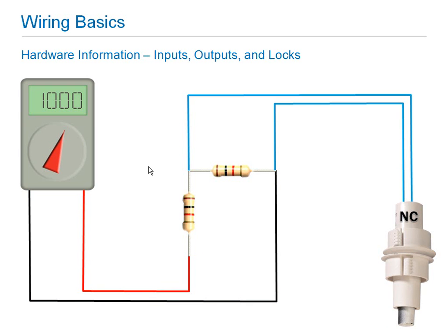Now we're going to close that up and take a look in the normally closed state. Let's say we get a short somewhere between the end-of-line resistors and the controller over here, which we've got the meter set up in its place. If we have a short before that, we can tell because we're not getting through to that resistor anymore. It's just going to the short and coming back, so there's zero resistance.